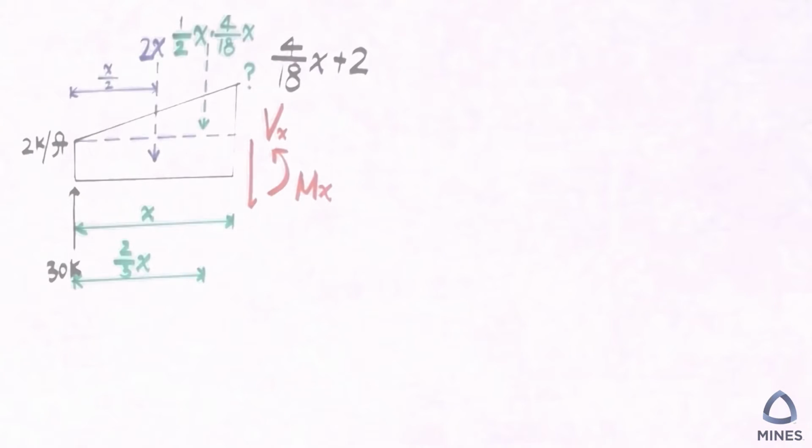After we find the shear function, we use the moment equilibrium equation to find the moment function. Here I highly recommend you summarize the moment at the cutting location, so that even if you made a mistake on the shear function, it's not carried on to the moment function.